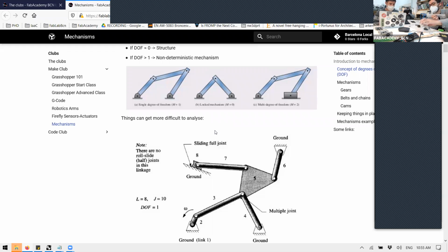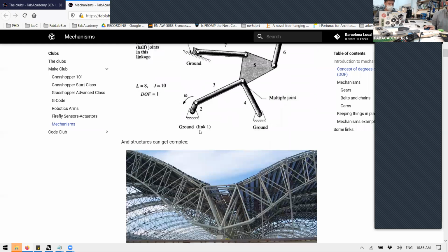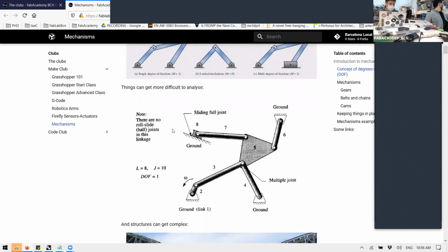For example, in this one, we are using a little piece of plastic, the white one there, to slide it. It is self-lubricating. It's a plastic that has a thin layer of oil that is being separated by the plastic. So actually we don't need to reduce the resistance mechanically. In general, we do that by using bearings that are really complex systems in really small packages. There are other ways of creating